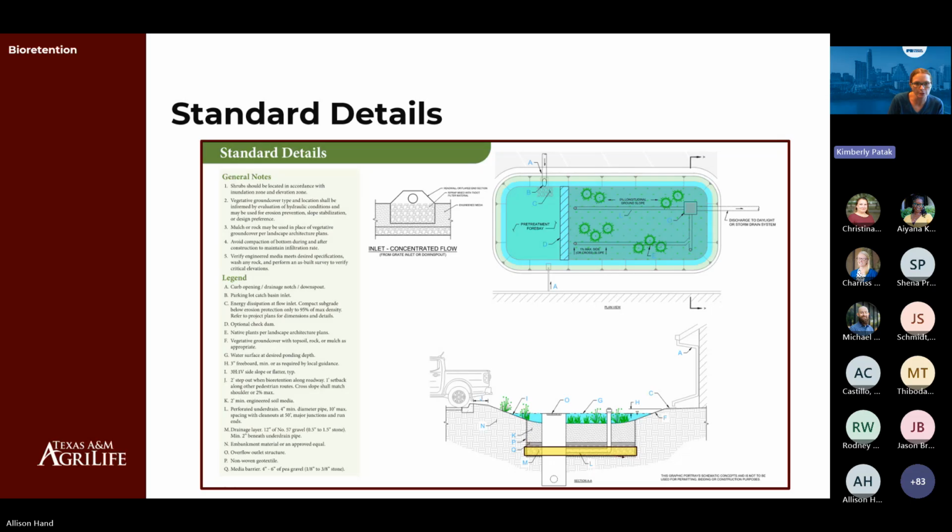This is where the underdrain would reside. And the gravel layer is comprised of a mix of 1/2 inch to 1.5 inch washed stone. Really important during construction to make sure that that material is washed before it is installed, because you do not want to introduce any new fine particulates into your system from the get-go. This layer is typically around 12 inches thick, but it is really based on the size of your underdrain.